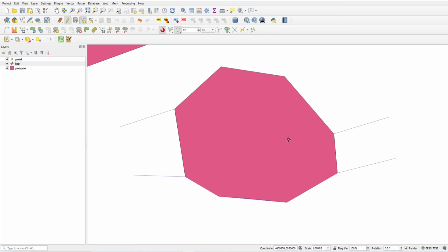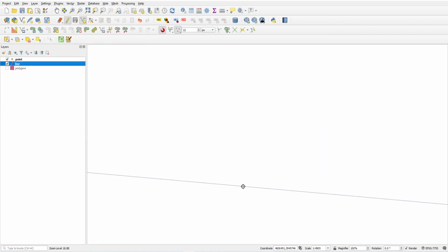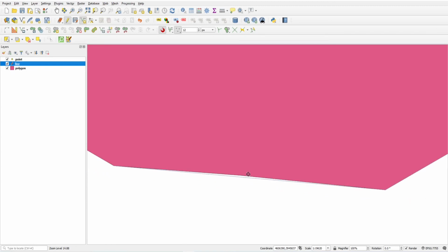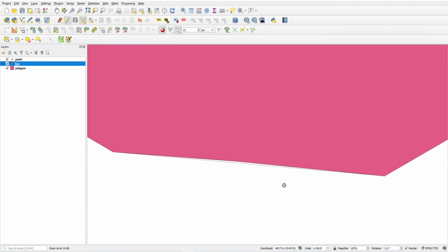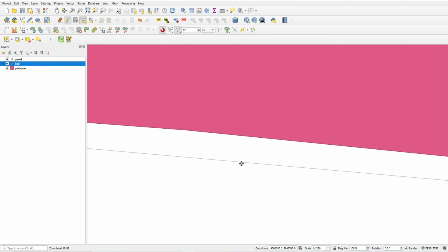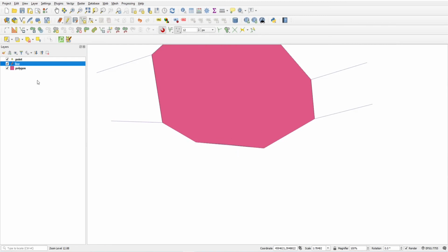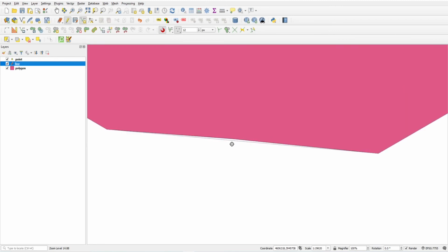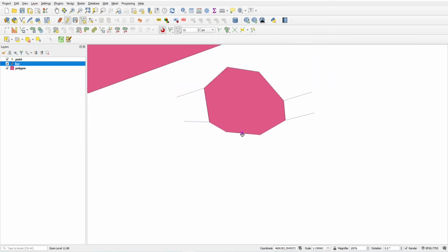Now my lines draw similar to as I draw above, but I turn off the polygon and you will see the difference here. I have not given this vertex for snapping, so this can be an error in GIS. This is a GIS not overlapping. And how it can be, we will do this. Just delete this line. I'm just deleting this line and click delete and save it.